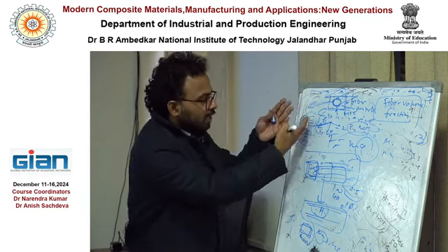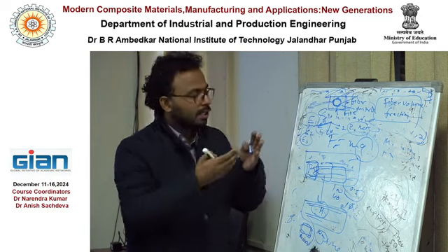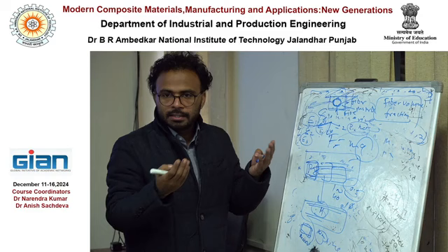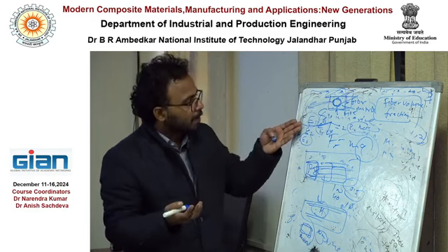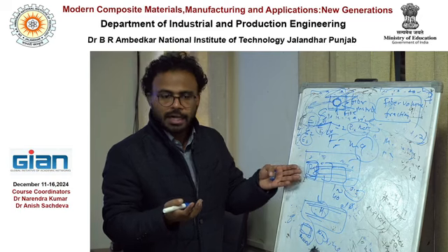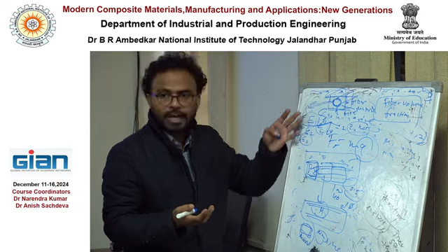So do this, and you will get E1, E2, E3, G12, G23, G13, nu12, nu23, nu13. Or for the transverse isotropic case, E1, with E2 equal to E3, G12, with G23 equal to G13, and nu12, with nu23 equal to nu13, right? So you got the 5 constants, right.